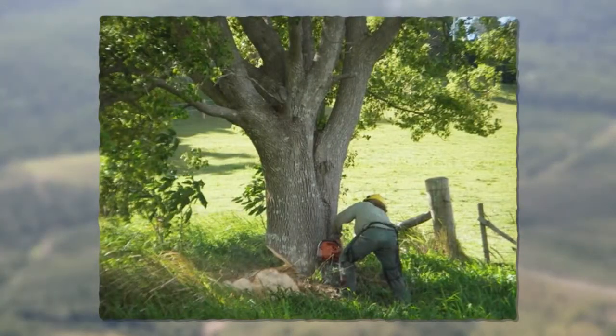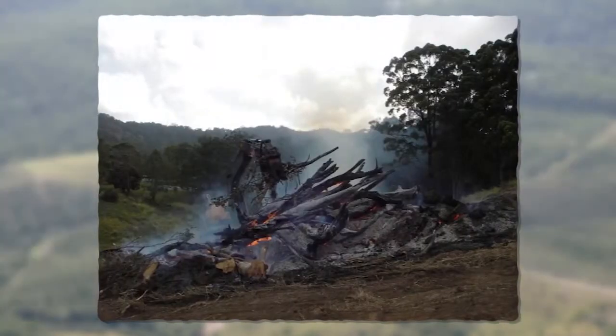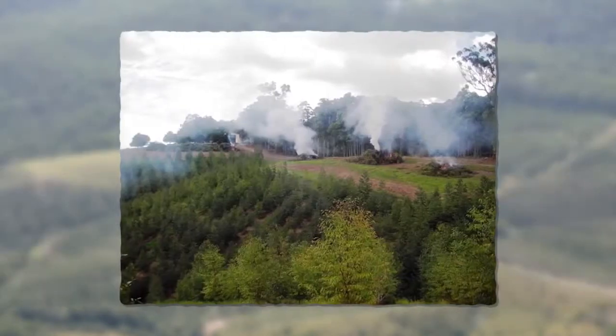Woody weeds such as camphor laurel should be removed and treated before site preparation takes place. Camphor laurels can be cut using a chainsaw, their stumps treated, and the material can be pushed into a heap for disposal via burning. These activities should be timed to occur in readiness for cultivation. That way the excavator can be used to assist with pushing and bumping up the stacks. The excavator is also useful for the construction of access tracks, erosion repair and removal of site rubbish.